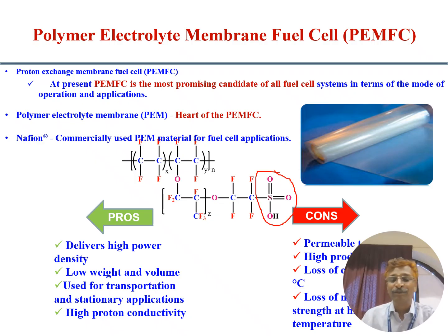However, it has some drawbacks. At elevated temperature, there is a drop in conductivity. So this drawback initiates researchers to find alternative membranes for Nafion. Okay. But still people are using Nafion. But there is another drawback: a highly complicated synthetic procedure for the carbon-fluorine backbone. So it is not an environmentally friendly manufacturing procedure. So these are all the things that induce researchers to find an alternative one.